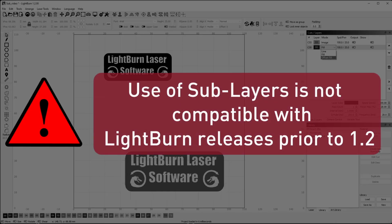Note: if a project with fill plus line layers is opened in LightBurn 1.2 or newer, fill plus line will be converted into 2 sublayers, a fill and a line. Once saved, you will no longer be able to load it into older versions of LightBurn. If this is important to you, please save a copy of the older file.